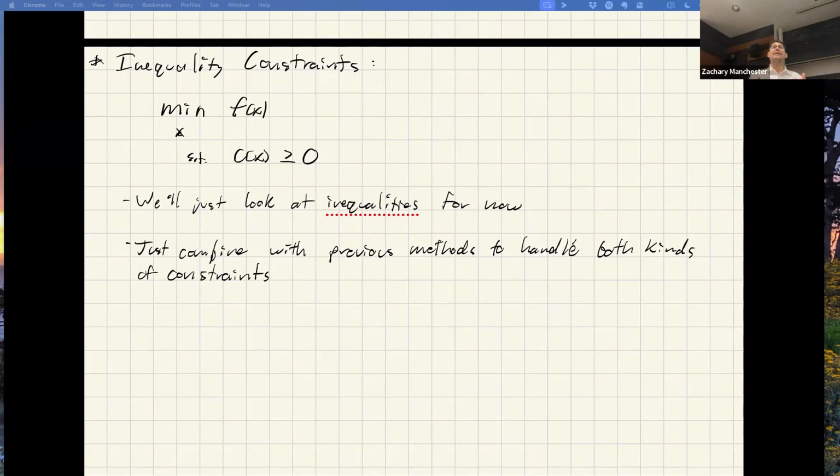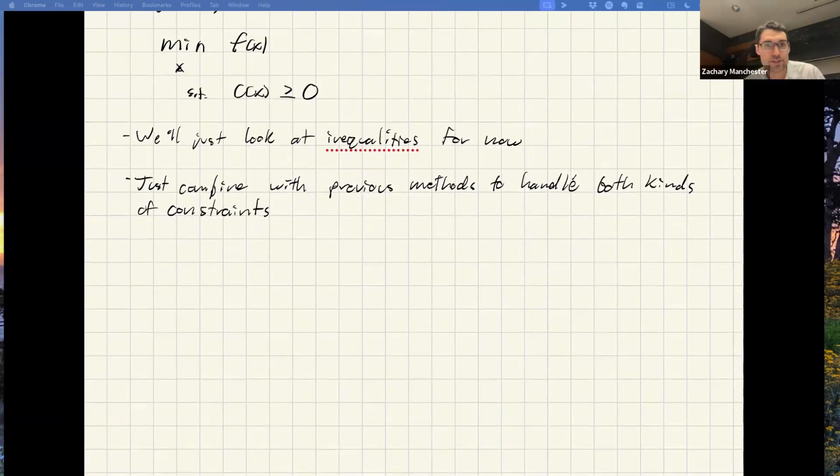On your controls. And they can also often show up as safety constraints, like keep outs. So usually we have inequalities on the controls to reflect actuator limitations. And then we often have inequalities on the states for safety stuff, keep out of, don't hit stuff, that kind of thing.